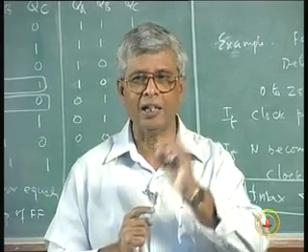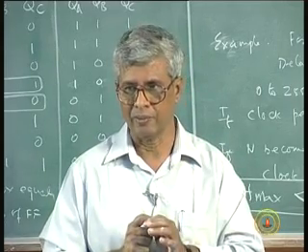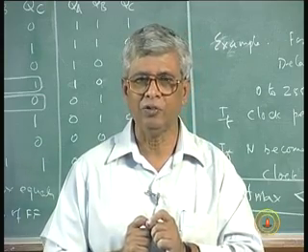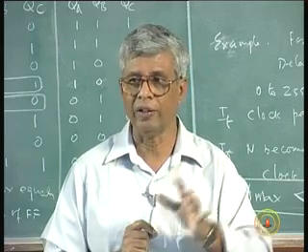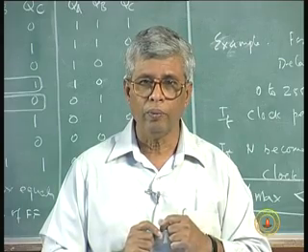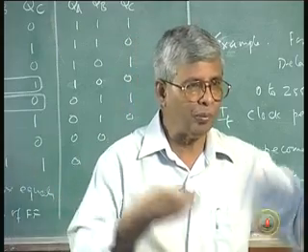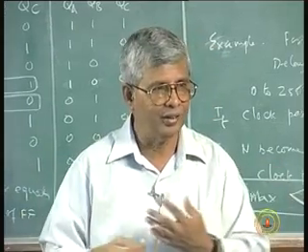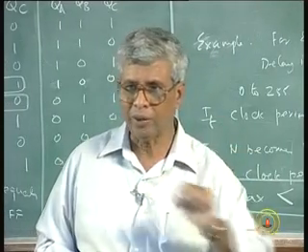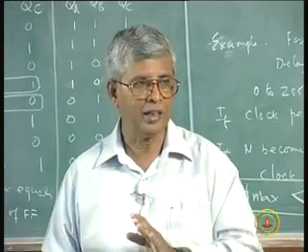As I said, the crystal oscillators were stable oscillators. There has to be a crystal, and these are only available in the megahertz range. So, you cannot always reduce the clock frequency for the reason of stability, sometimes it is possible, not always, or you want a particular speed of counting. For my application I need to count this fast, events keep coming. If the number of people I am going to count keep coming constantly, or some small atomic events you are counting, you keep counting at the rate at which it has to come into the count. You cannot say I can only count at this rate, so please slow down, I cannot say that.